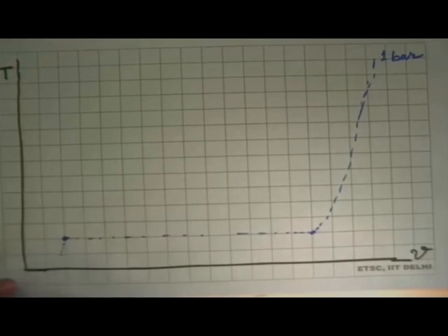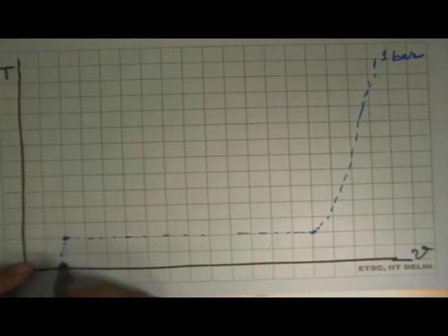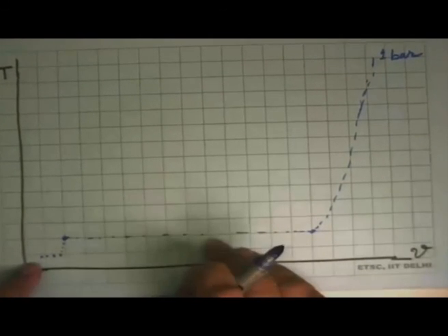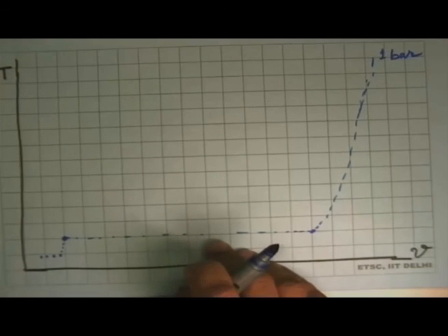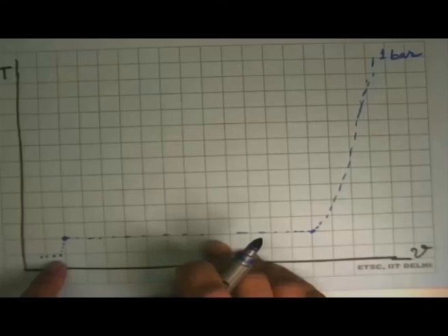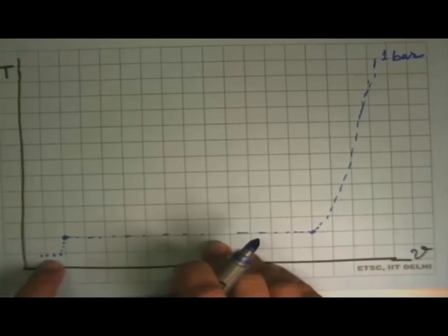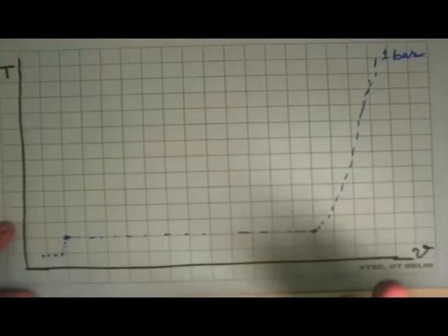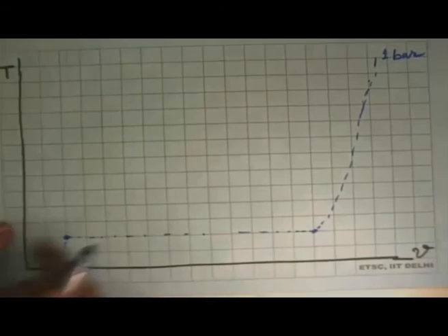Now what will happen if we do it at 10 bar? Well, let's say that if I start from the same temperature, 40 degrees Celsius, and increase the pressure to 10 bar, 20 bar or something like that, those states will go this way. I am exaggerating a lot, but in reality the change of volume of a liquid is very, very small. And you can see the plots, there's practically no difference between these densities. But just to illustrate the point, I have pulled them out. In reality, they are not that far off. Simple reason, in school we have learned liquids are incompressible. That's the manifestation here.